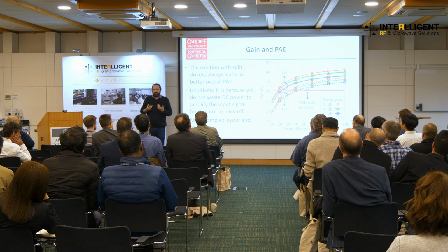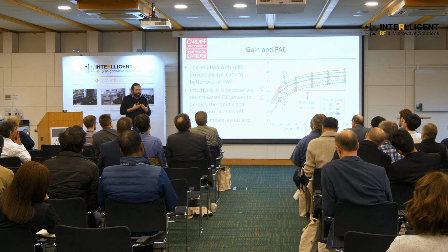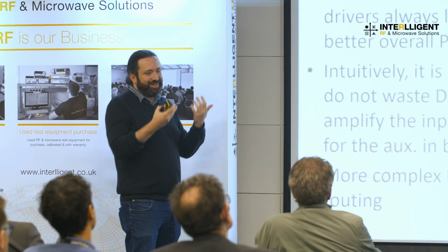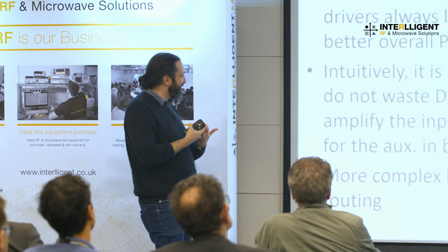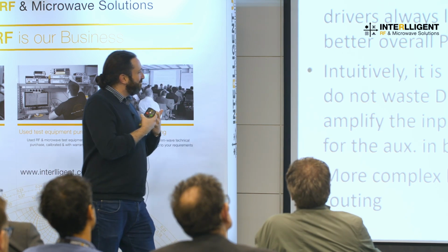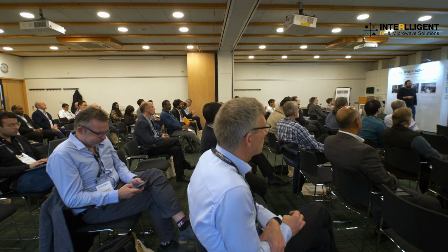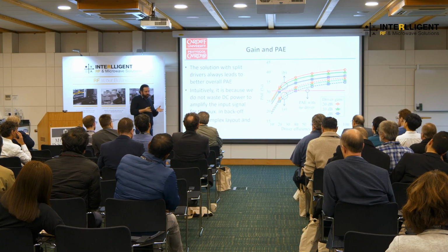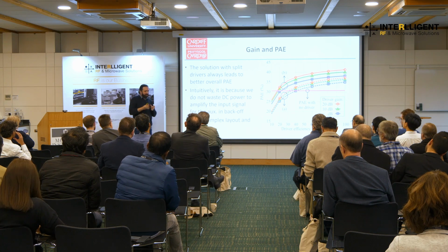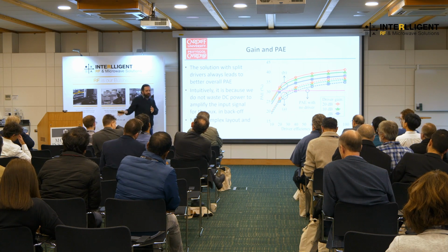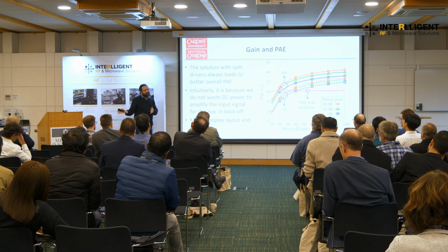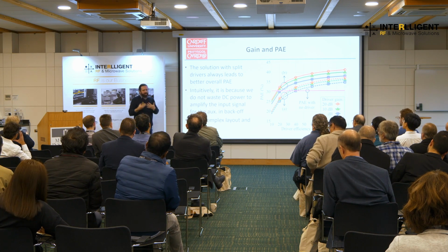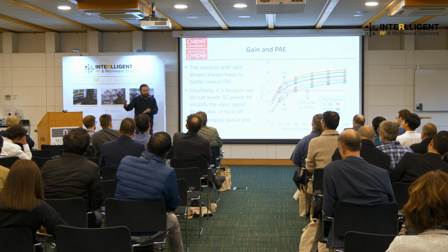Now, we did all these calculations, and then after publishing the paper, we start thinking, well, isn't it that, probably, I think someone came to us and said, well, that's obvious. Yeah, thank you very much. You could have told us months ago, right? And they say, yeah, of course, because what you do when you put the single driver in front of everything, you're amplifying the signal that you're then splitting, and part of it goes into the auxiliary and is not being amplified. So you're actually spending DC power to amplify a signal that is never amplified later on by the final stage.